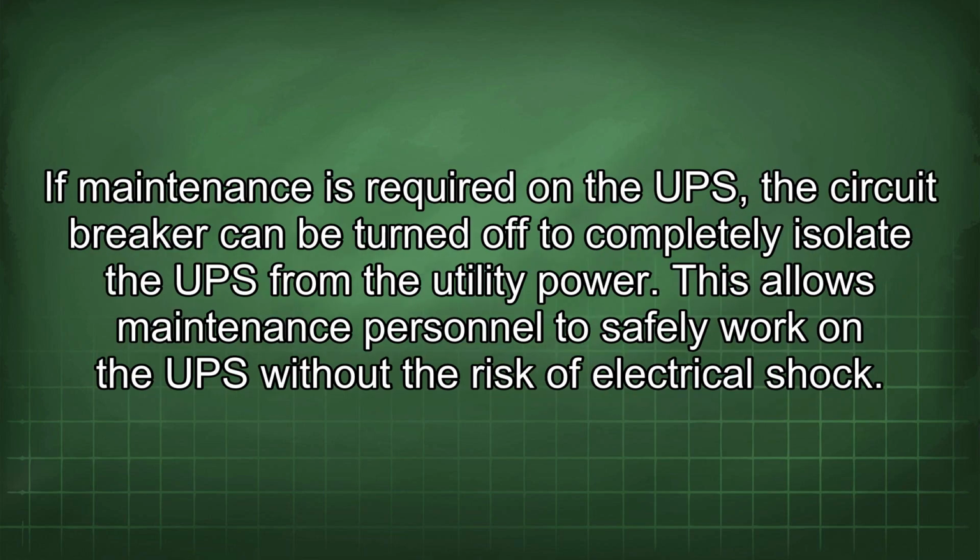If maintenance is required in the UPS, the circuit breaker can be turned off to completely isolate the UPS from the utility power. This allows maintenance personnel to safely work on the UPS without the risk of electrical shock.